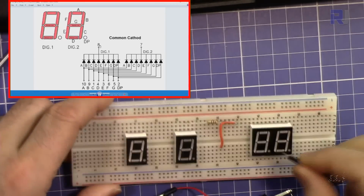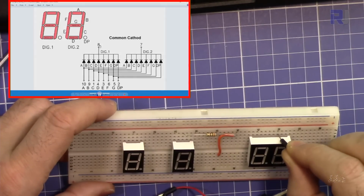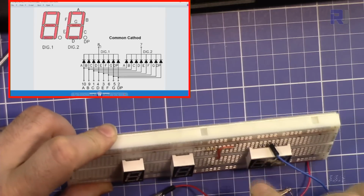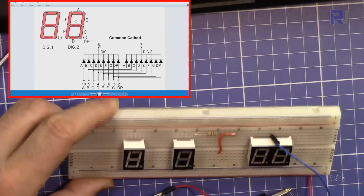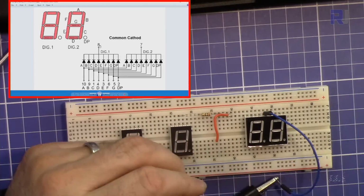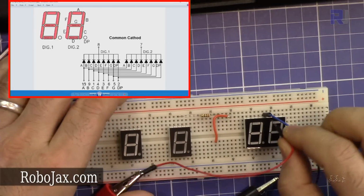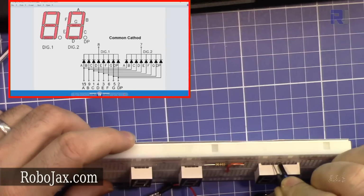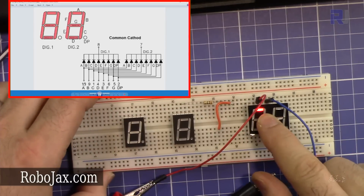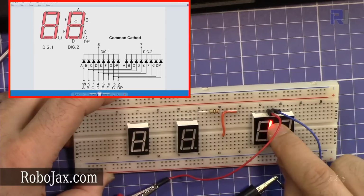Now let's turn it on. So 1 to 5 here, this is 6, so that skips the 2, that is 6, 7 and 8. Now I'm connecting at 8 and 2 more pins left, as you can see here. Now to turn on segment A, as you can see on the diagram, I have to connect it to pin number 10. So that was 8, 9 and then 10. 10 is for A, 9 is for B. If I connect 9, that's A and B.